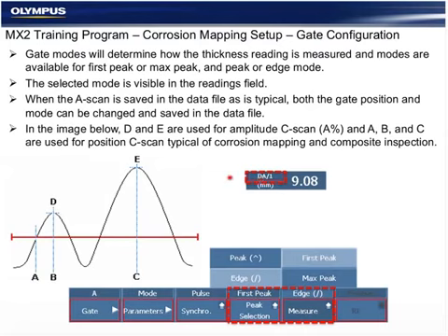In amplitude-based weld inspection, we generally use either the first or highest amplitude peak to generate our C-scan and color palette. In the corrosion mapping, the applicable readings are the first leading, first peak, and max peak points.